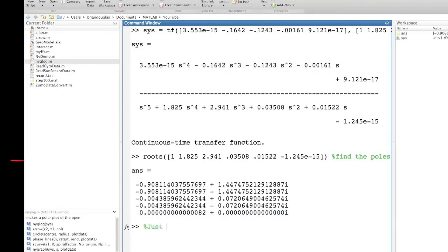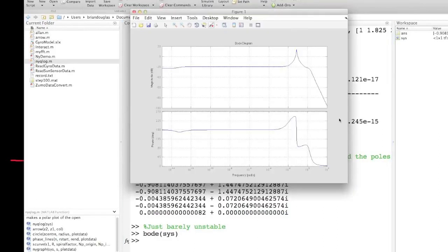Let me first plot the Bode plot of this system and see what closed loop stability information we can get from it. And it's a bit hard to read. Even if I show stability margins in the normal sense, you can't easily tell if the closed loop system is stable or not. And in some open loop unstable cases, you can't tell at all. Therefore, in this situation, you'd be safer just to plot the Nyquist plot instead.